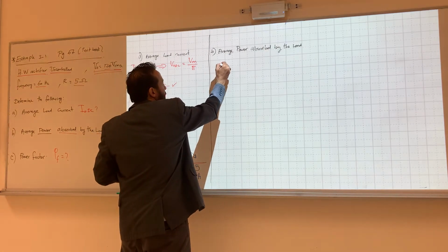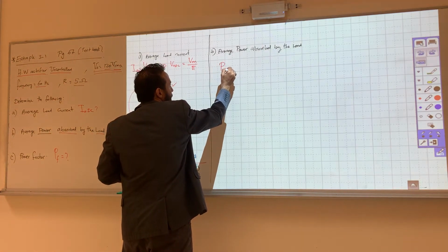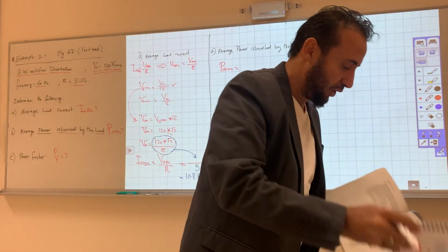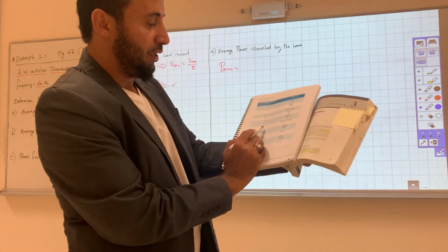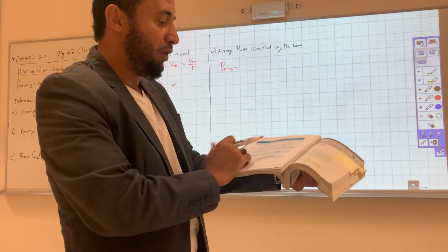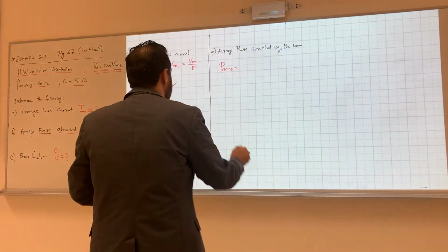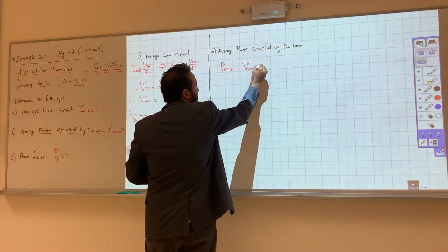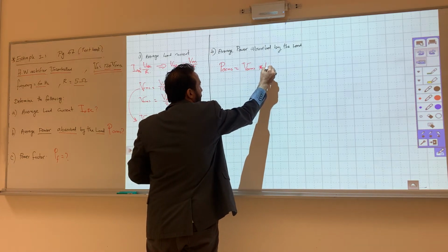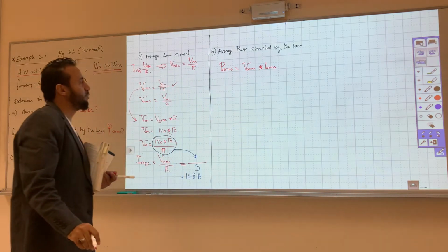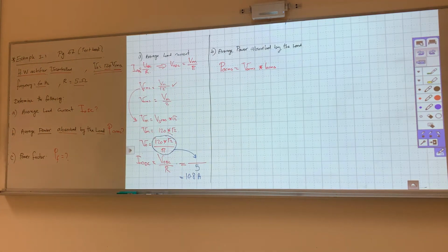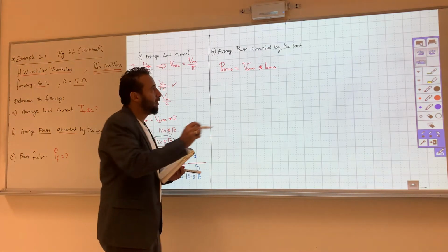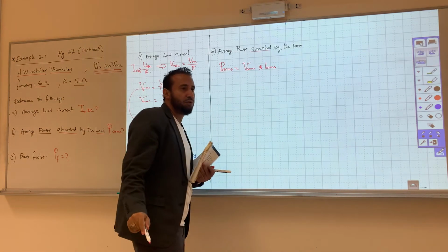So now P out RMS. Ohm's law, guys. Same thing, you're going to find the equation right here. See here, P out RMS, I am in page 11. It's I out RMS times V out RMS, Ohm's law. So you can say here, V out RMS times I out RMS. To find the P out RMS, or the power absorbed by the load, again, you need to pay attention to this word. When they say absorbed, it means RMS.